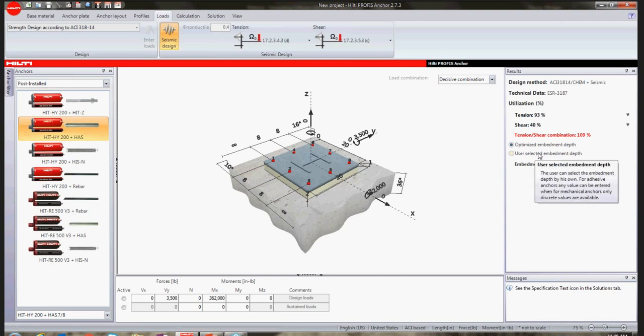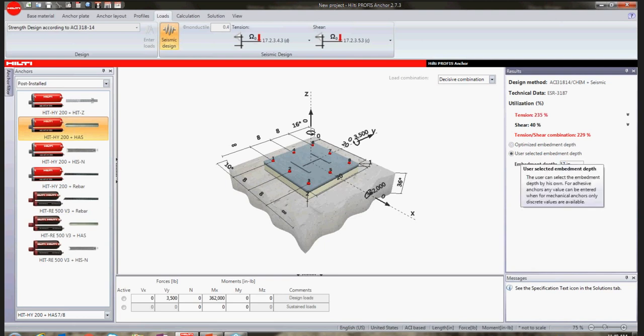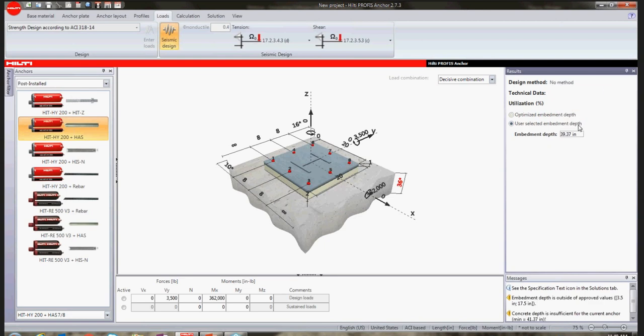It's going to default to this grout pad height. We're going to change it to 2 inches. But the one I want to focus on is the rotational restraint. So the rotational restraint varies from 1 to 2. Essentially 1 meaning we are allowing the fixture to rotate, or 2 means no, we have full fixture restraint.